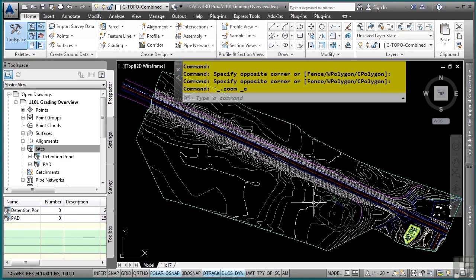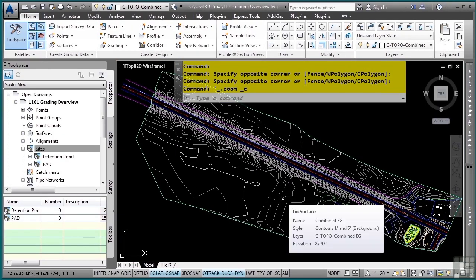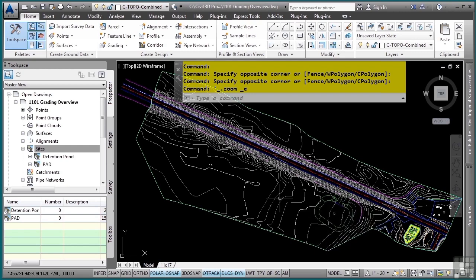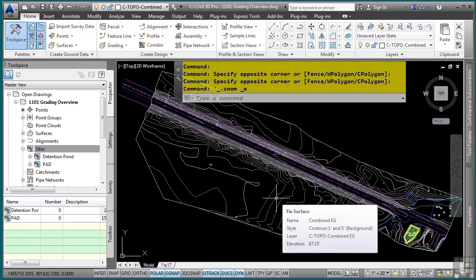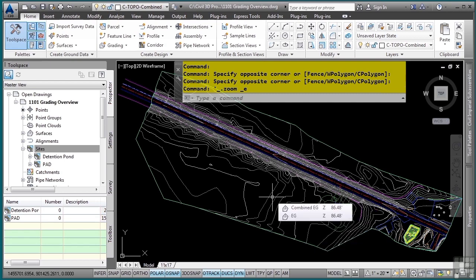The grading tools and commands in Civil 3D provide a flexible interface that you can use to create almost any type of grading objects. You can automate surface creation by using grading criteria, such as grade to relative elevation, grade to distances, and so on, as well as feature lines. You can define grading styles and criteria and feature line styles in a drawing template to save time, drafting, and help create consistent, standard-based drawings.